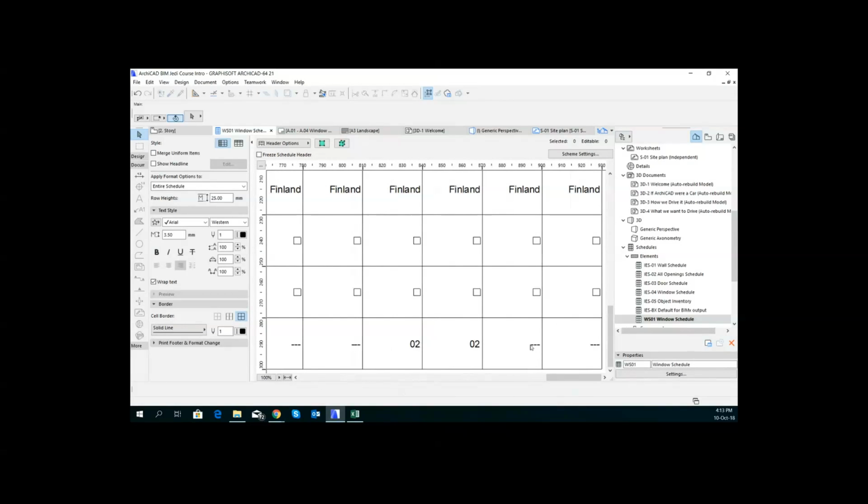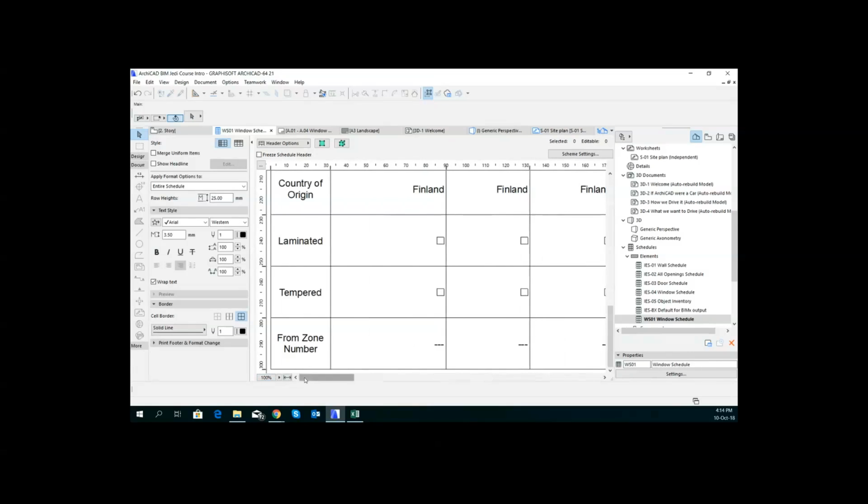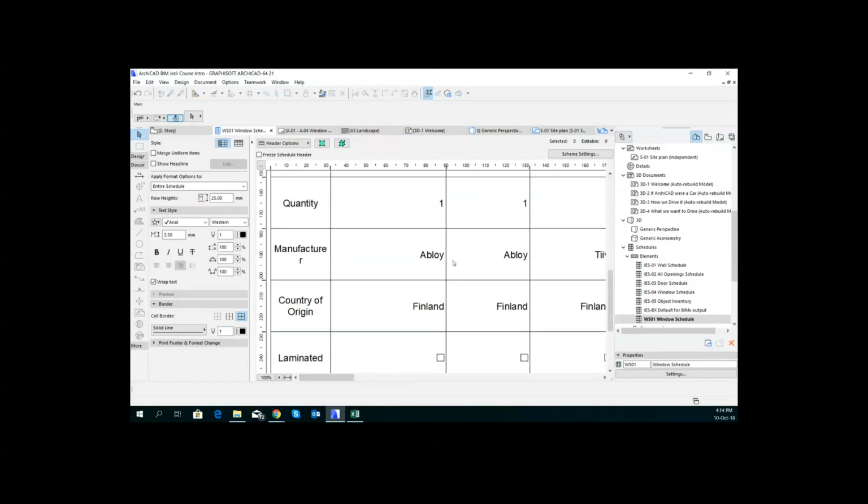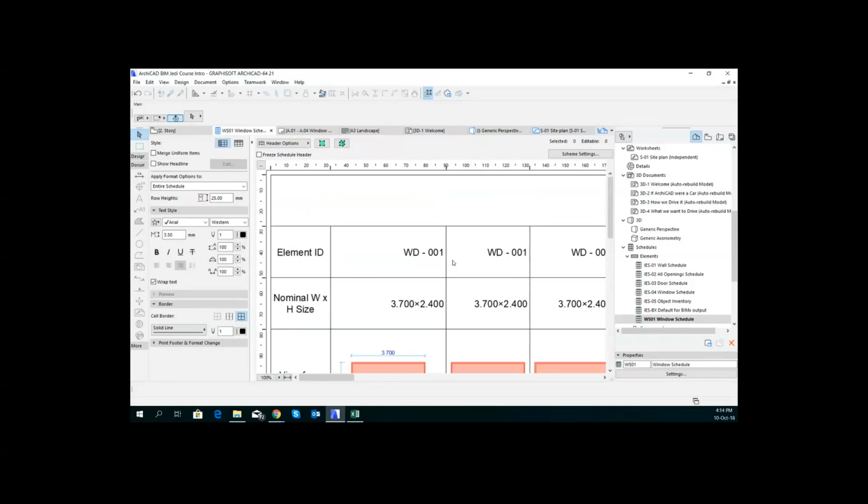where it's going. But then you have to make sure that the zones touch all the corners of the walls as well. If your zones are out fractionally, that wall won't register as being part of that zone. That must be fun. And if you change the wall thickness somehow, then all this collapses. Yeah, there's no way of setting zones that are, what would you say, associative, so you can change. I know there is, and that can be another lesson.